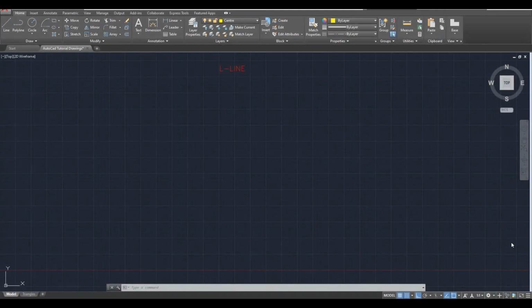So we're back over in CAD, where we are looking at our line tool. Our line tool is activated by simply hitting the command line, ensuring that you're on CAD, and typing L, and then hitting enter, and it's going to ask you to specify your first point for your line. However, I'm not going to go ahead and do that. First, I'm going to speak quite shortly on the ortho and polar tracking, which are basically helpers for our line tool. If we're going to use the line tool, you want it to have direction.